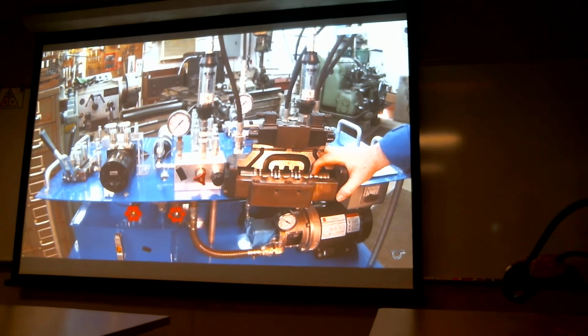Okay? One of the things that I often hear when I go in and out of facilities is, it's mechanical. No, it's electrical. It's mechanical. No, it's electrical. All right, only these directional valves right here, this right here is called a manual override. Okay? So at 2 o'clock in the morning, if your actuator isn't moving, you can get a push pin or a little Allen wrench or something and come over here and push that right in, and it'll manually shift this valve. So if your actuator goes out or your motor starts turning, then that tells you you've got an electrical problem. Okay? So that's one of the biggest things I run into out there at 2 o'clock in the morning.